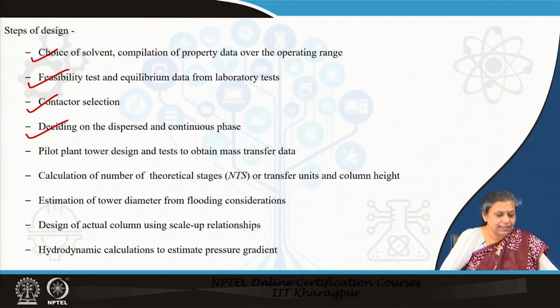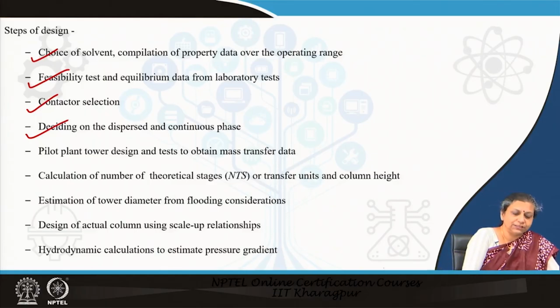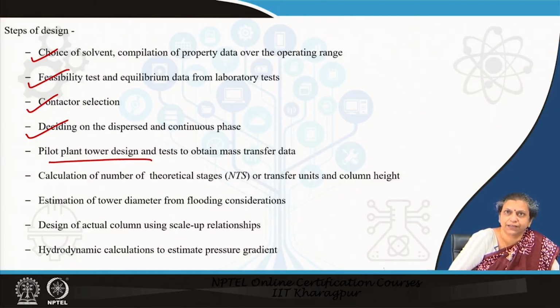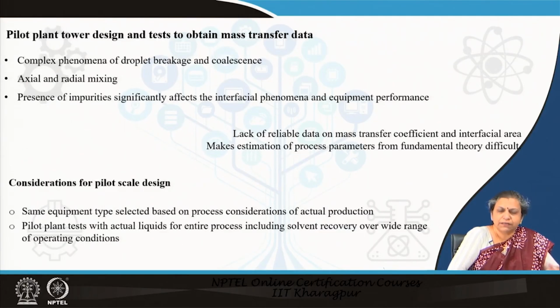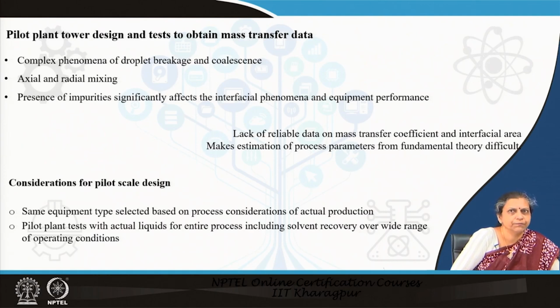Now, the next thing which is very important is the pilot plant design to obtain the mass transfer data. For the mixer settler, if you remember, I had derived the basic equation for the holding time. We found that the holding time was a function of the mass transfer coefficient and interfacial area, and I had also mentioned that in this case there are a large number of uncertainties. Why?